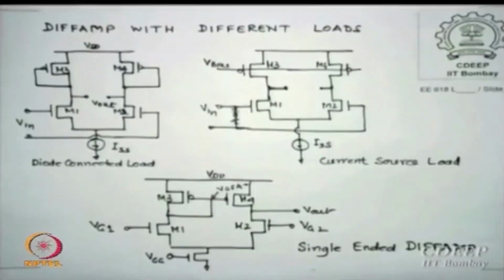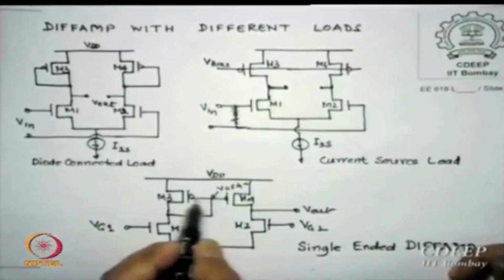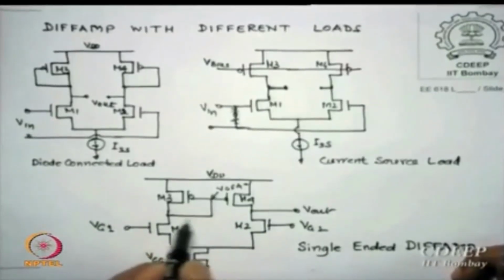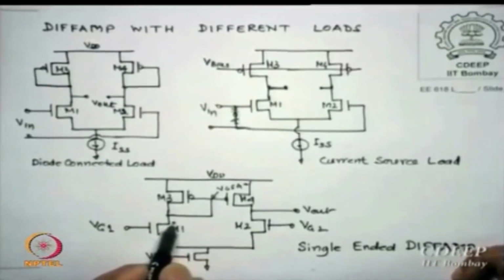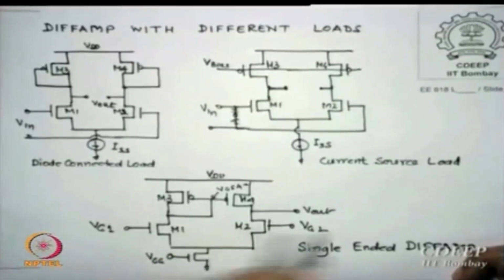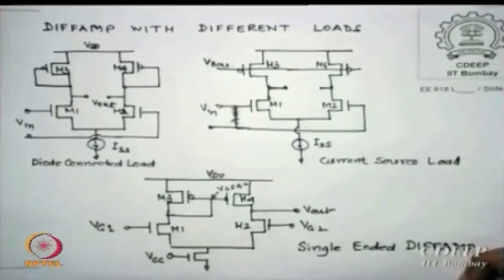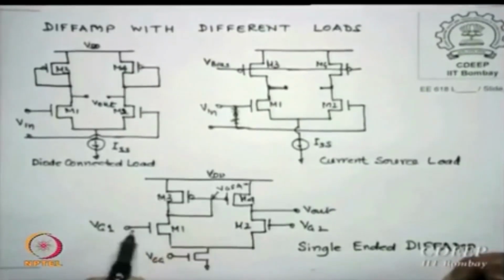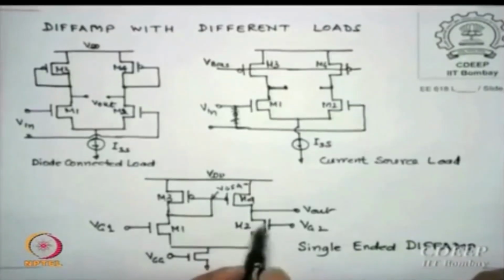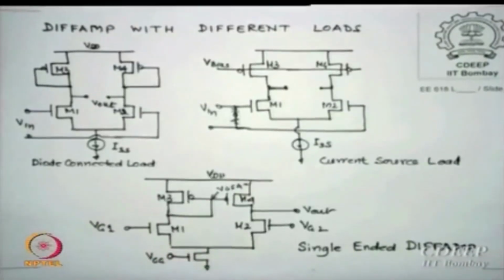The feature is very interesting here because here the two p channel gates are connected to one of the drains of this side. At times you can do the other side also, then the output will be the other end. They are symmetric, so it does not matter, but normally it is shown this way everywhere, so I am also showing it this way. You can as well do it here and then take the output from there, it is only a question of mirror.